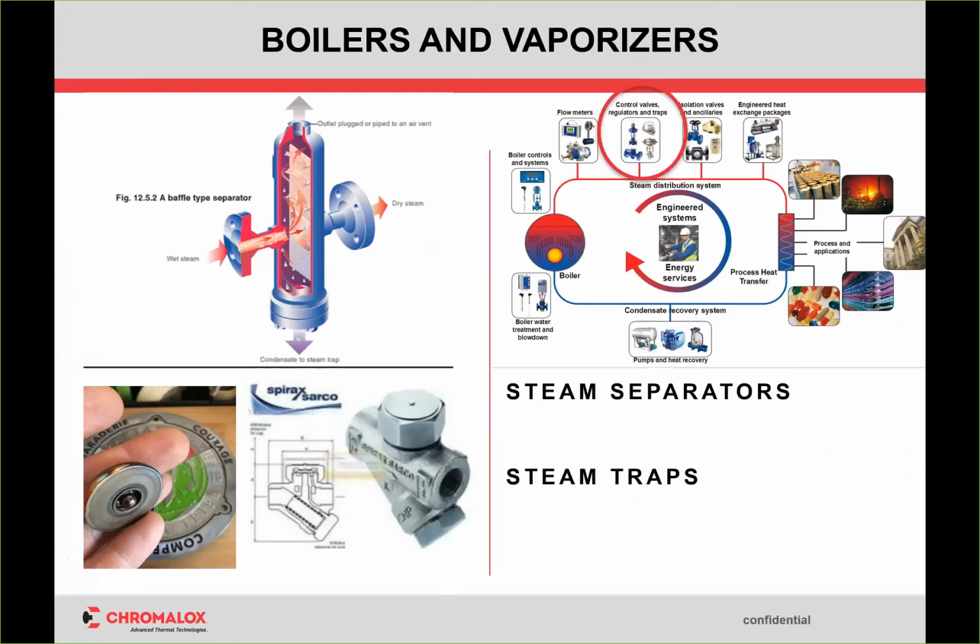Now, on a boiler loop, oftentimes they're gas fired. The boiler's on the other side of the building or whatever, and all those steam lines, the quality of the steam starts to condense. So we talked about steam traps. Steam trap is just the industry term. The steam trap itself is not catching steam, it's catching condensate. Condensate is where the steam obviously turns back into liquid. It's given off its BTUs, its thermal output, on its way there, and that's your line losses.